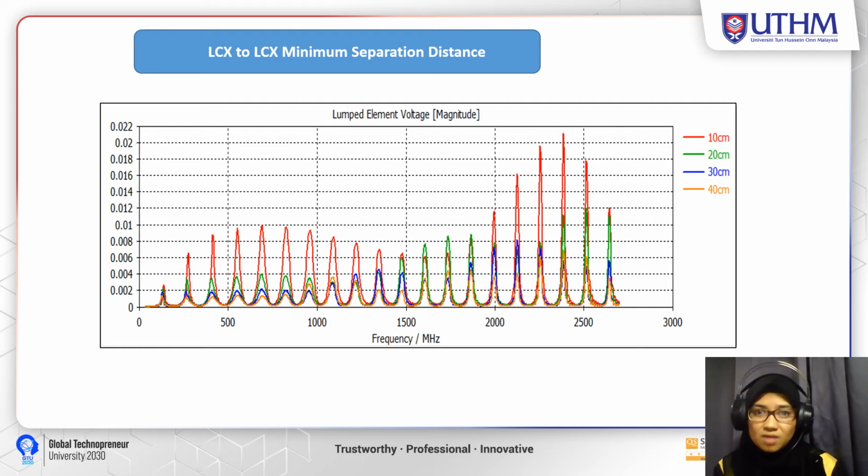From the result, it can be concluded that the minimum allowable spacing between linking cables is 0.3 meter. Some clients ask for more separation to install the linking cable, but with the data, it can be proved that 0.3 meter is enough, because even if the separation increases, the induced voltage will only change by very small values.